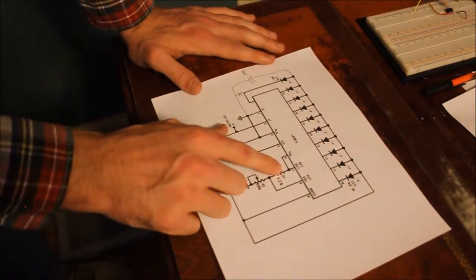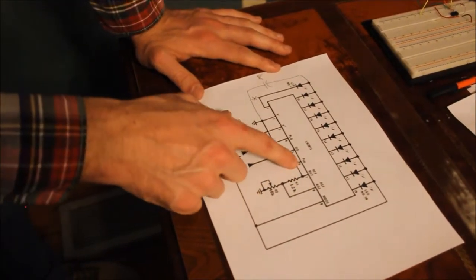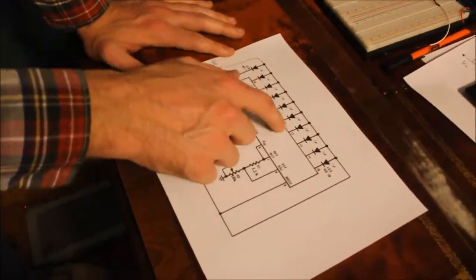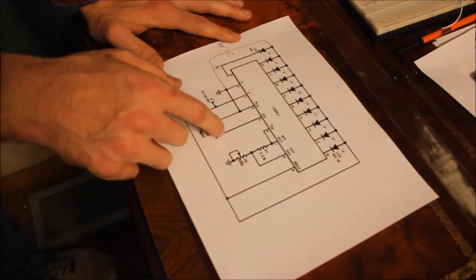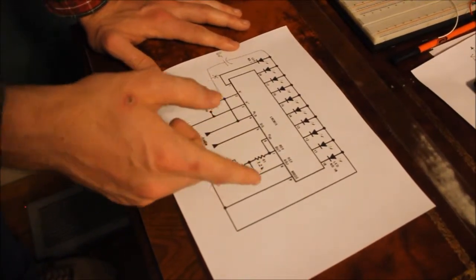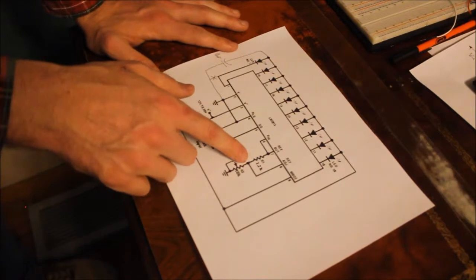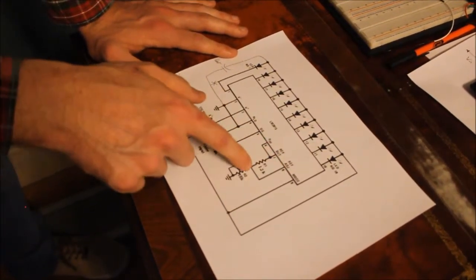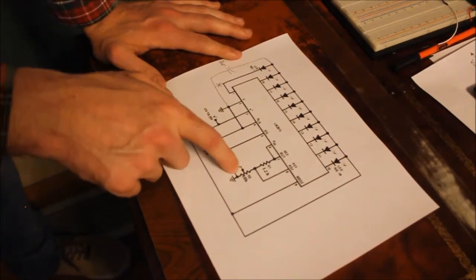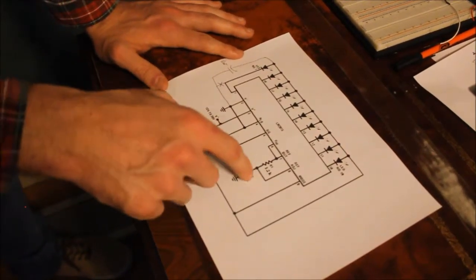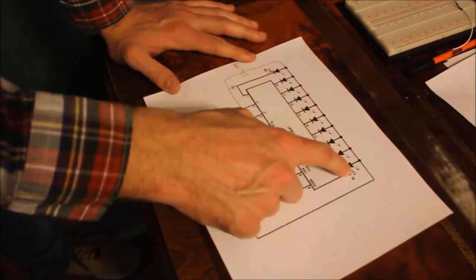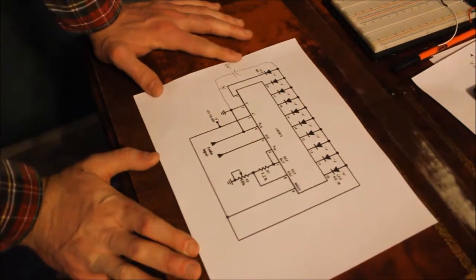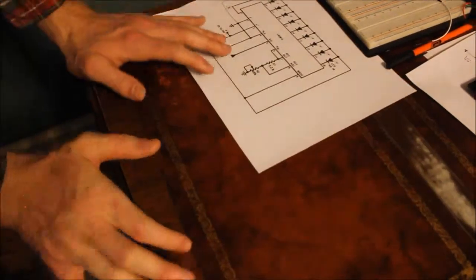Over here you can control the brightness of the lights because pins 8, 7, and 6 control the output voltage at these terminals. What you can do is set your R1 to 1.2 kilo ohms, and then between this connection to 8, in parallel with R1, and ground, you can put a potentiometer. When you turn that potentiometer, you'll be adjusting how bright or dim these lights will be when an input signal comes in. So that is the schematic and how all the pins work.